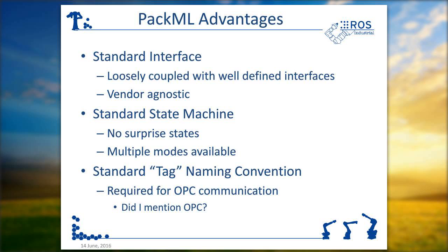OPC is really just an old-fashioned way to have a Windows computer talk to a PLC through a network communication. And if you want to use it with a Linux computer or something else that doesn't require DCOM, then you can use OPC UA, which is the new version. It's much better, but it still isn't widely implemented in industry here in the U.S.